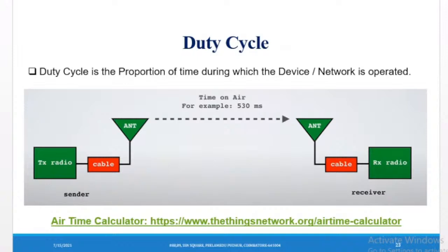So what is duty cycle, and why do I have to go for this? I'm mentioning that line of sight is there, and the data is pushed from the node to the network server. How much time does it take? I'm unable to get that yet. With the help of duty cycle, we calculate the time taken from the node to the network, the air time of the data transmission. How much time is it taking? We are going to calculate it now.